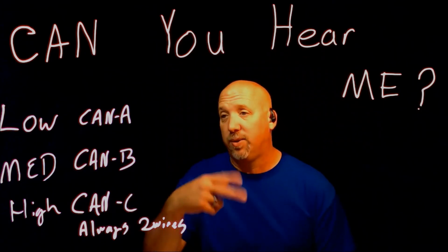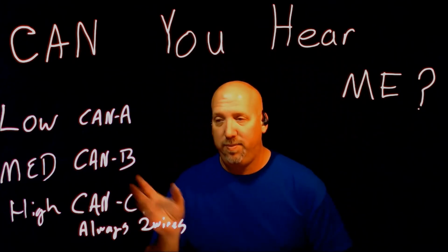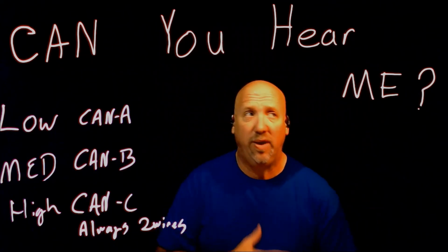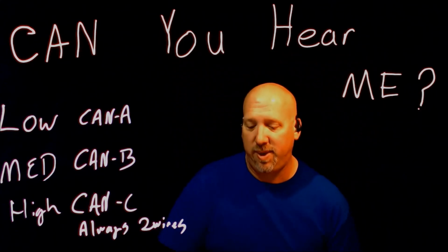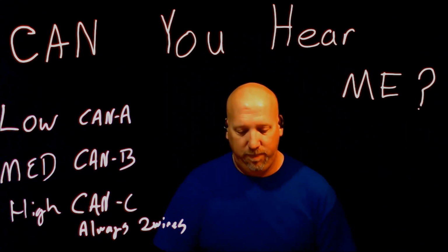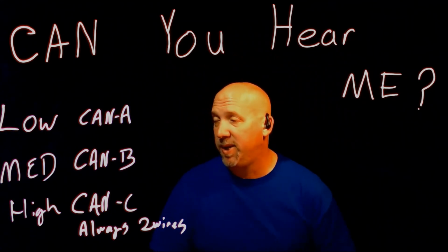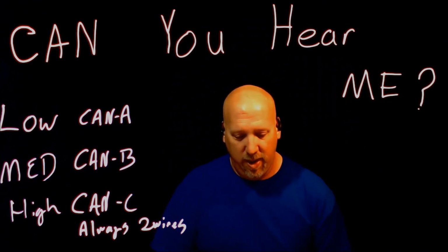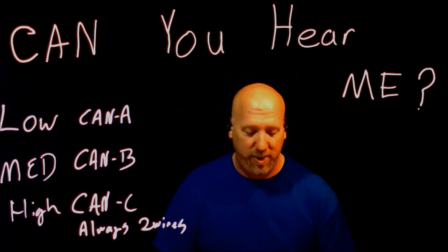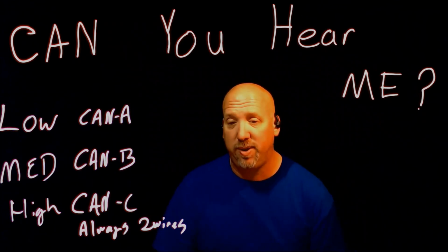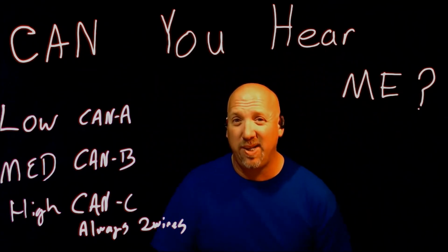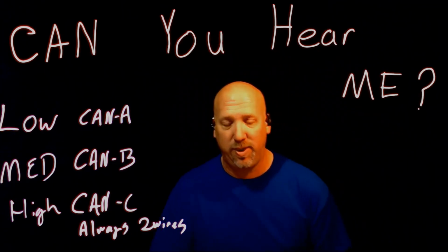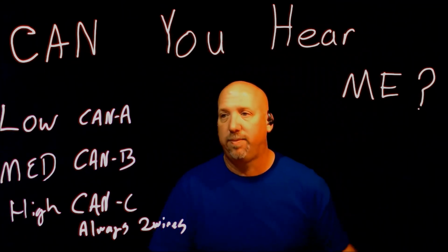Then we have the cyclical redundancy checks. Remember the redundancy bits that follow each message that is sent out. And you've got a very stable network with CAN systems now. Modules keep sending until each message is completely received and verified. So momentary interference or interruptions only delay communications. The message is still going to get through. It's just maybe delayed a few seconds or milliseconds or microseconds, depending on what it is.